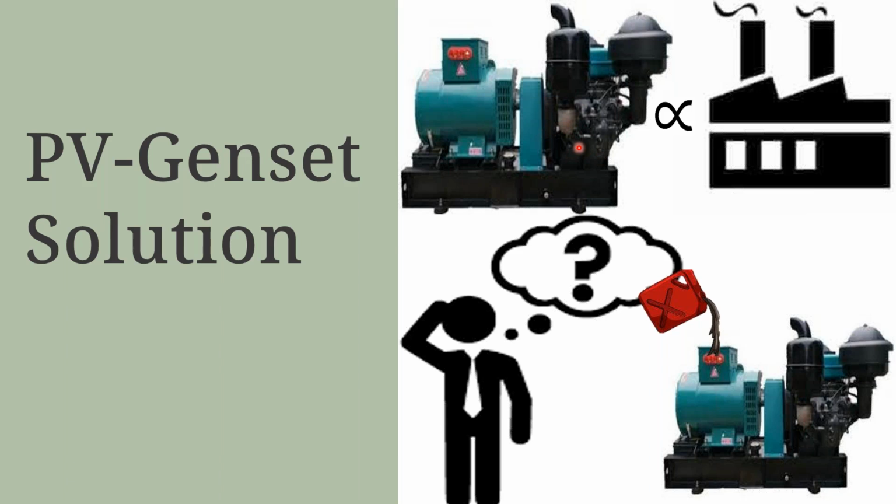What happens is, if a heavy load is turned on, the demand for power increases from the load side, obviously. So there has to be an increase in power coming from the genset. This is only possible if there's an increase in the fuel quantity coming into the combustion chamber. So the governor pulls the valve open, to allow more incoming fuel into the combustion chamber.